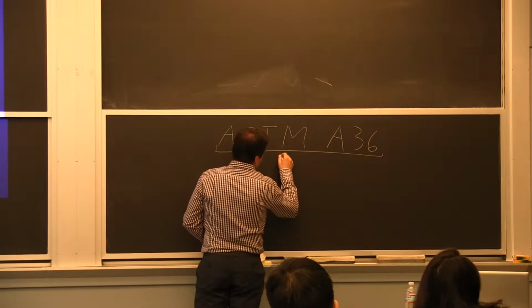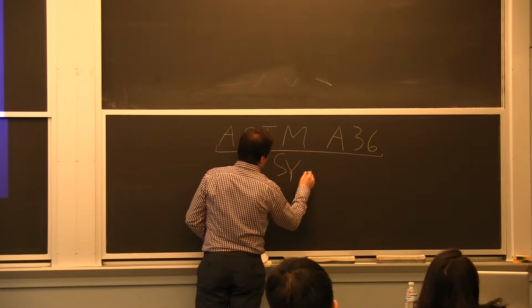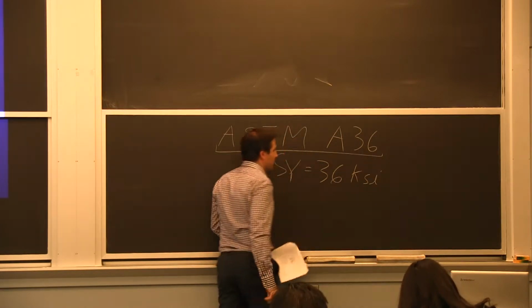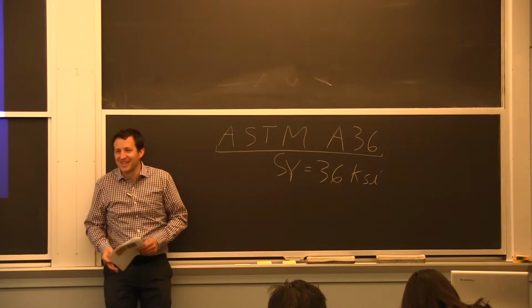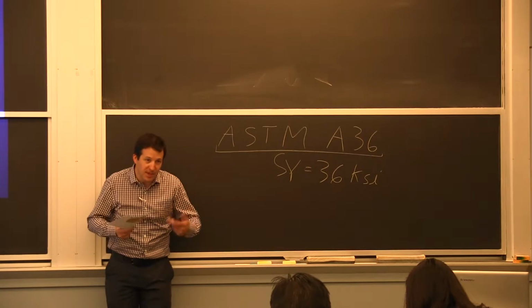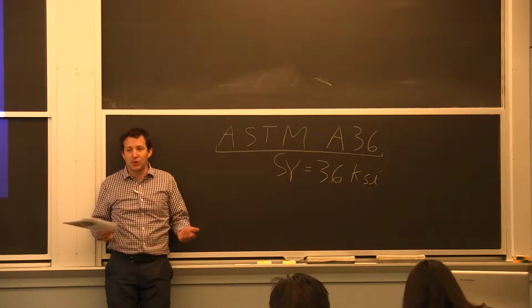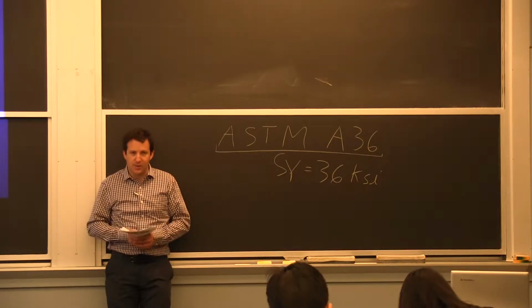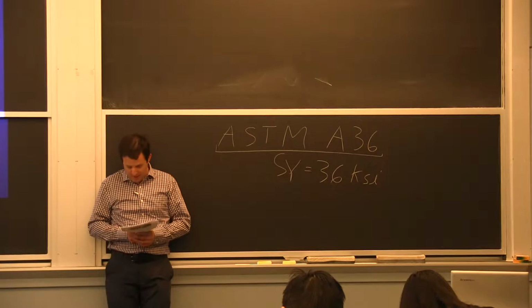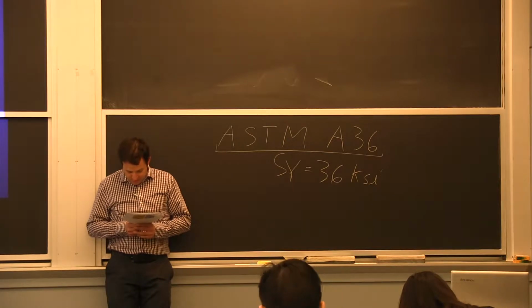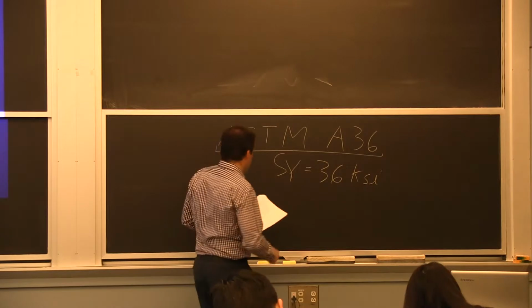And that could be easy for you to remember, it's A36. It's the only one that has this correspondence. It just happened to be, it's a very old standard. It's been updated over time, but when they decided they were going to do structural steel, they decided, okay, the minimum we're going to ask for is that 36 KSI initial yield strength. If you look into more of the detail, it tells you the tensile strength is going to be between 58 and 80.